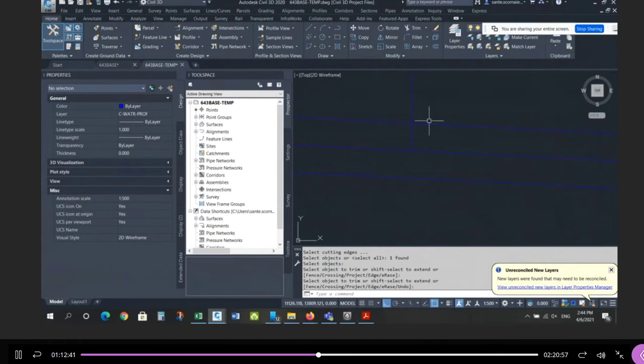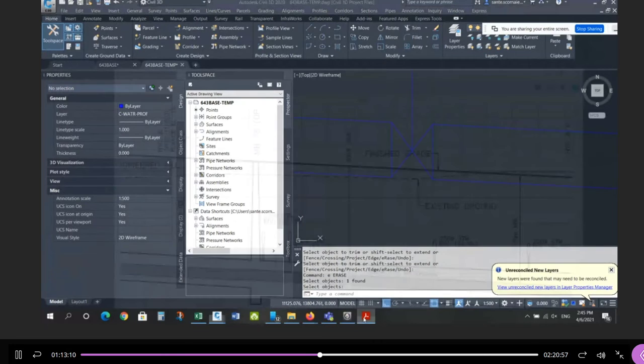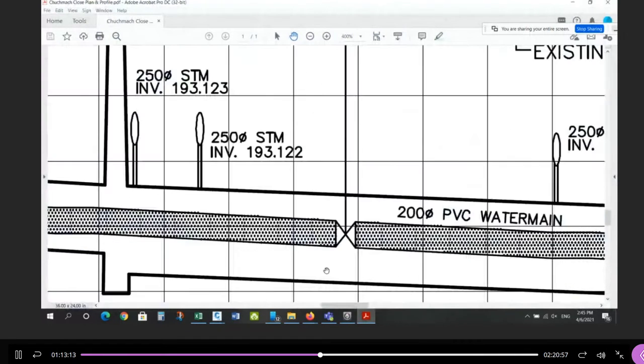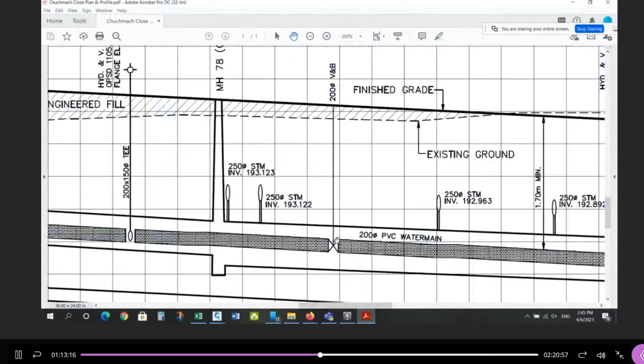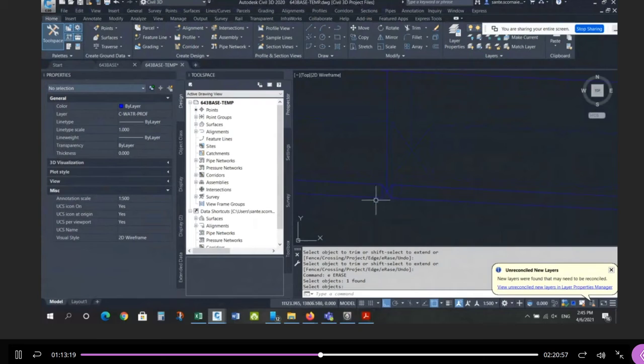It looks like it's not quite 90 degrees in there. So I'm just going to offset, if this is 200, I'm going to go 100 each side, 0.75 each side. So this way and this way, extend to the bottom. And then I'm going to draw a line from this intersection to this intersection, and from this intersection to this intersection. And then I'll trim this here, and then I'll trim between these two lines here. And then I don't need the line in the middle, and that looks a lot like what I see here, right? Exactly what I see here. So I drew this vertical line, I put an X there, I draw a valve box, and that's my standard for it. So that's how I draw the valve box.